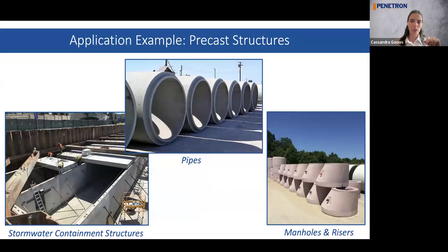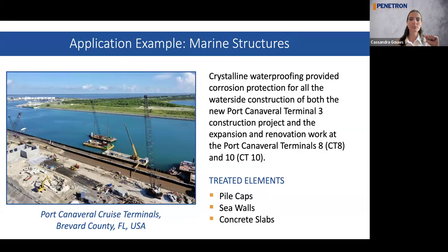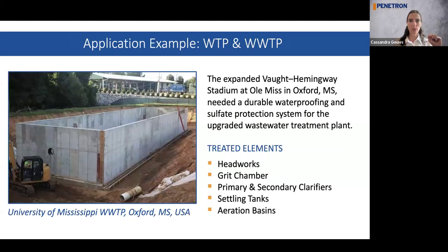Any precast structures that need to be waterproof or protected from sulfates or chlorides, that would be a very good example or application. And then marine structures, so anything that's exposed to these chlorides and sulfates for corrosion resistance. So whether it's pile caps, sea walls, concrete slabs, all very suited.